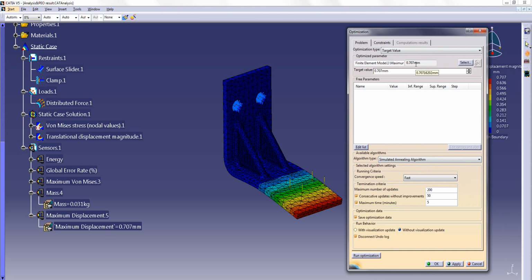The current displacement is 0.7, and maybe I want to achieve, okay, let's say I want to achieve 0.3, but I put a bit lesser value, because usually for optimization, sometimes we would not get that value exactly. So if I aim a bit lower, maybe I can get the value. So if my target is 0.3, maybe I can put 0.29 as my target value.